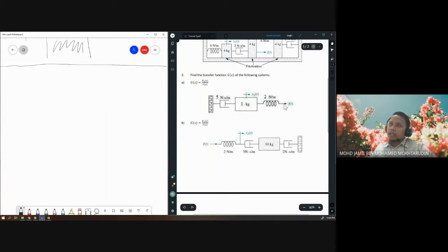So when you find cases like this, when there's a force not connected on the block, but instead connected in front of something else, you need to create or add a degree of freedom on the F, or in between the F and the thing that it is connected to. So in this case, you need to add a degree of freedom on F. Maybe x2 here.